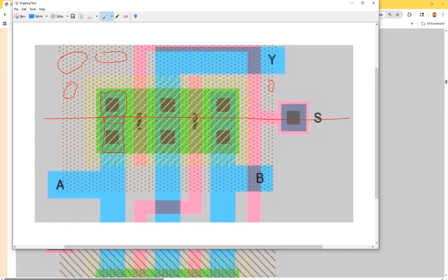Metal one, the light blue metal one. Vias. That via, keep in mind, it's a P plus to metal one via. It's directly going up. Poly goes through. That's why it shows this weird color, because it's an overlay on the top of the green. Here, this one, make sure you do it correctly, because it has 3 different layers: poly, metal one, and via.